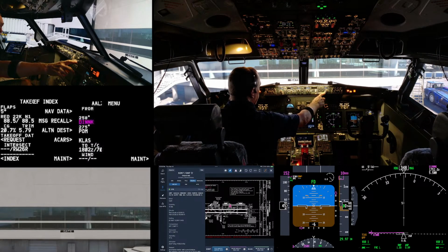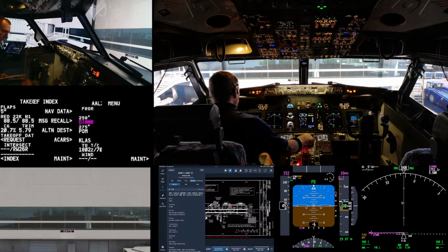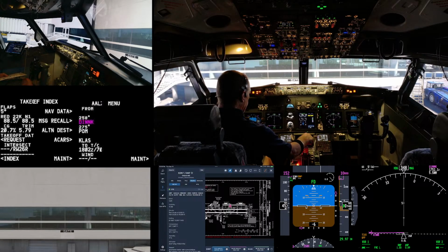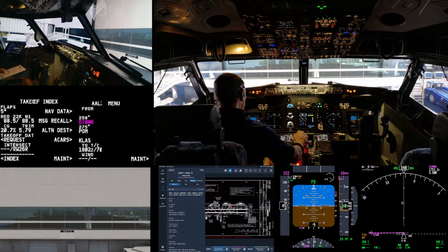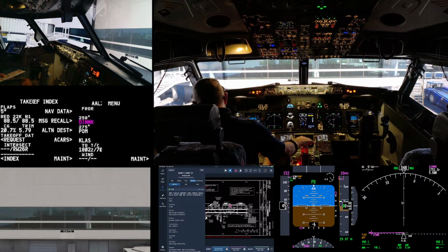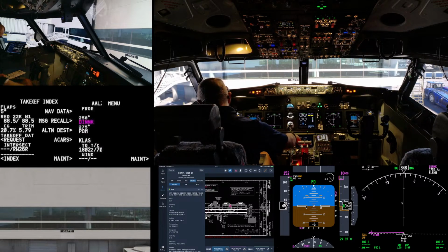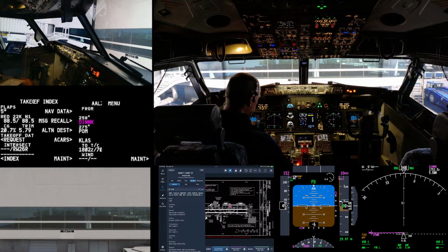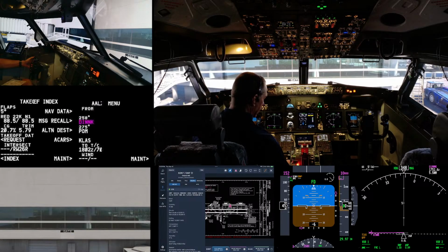Flight director's master is captain side, and that's good. Autopilot disengage is up and confirmed. All checked. Throttle takeoff config confirmed. Speed brake is verified down detent. Reversers are down. Flaps are up. Parking brake set. Confirmed. Fuel cutoff is in cutoff mode. Stab trims test. Check.